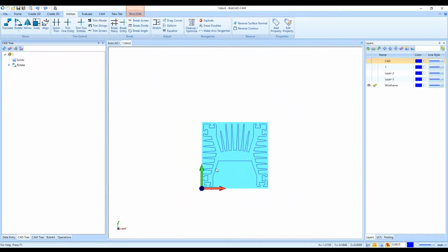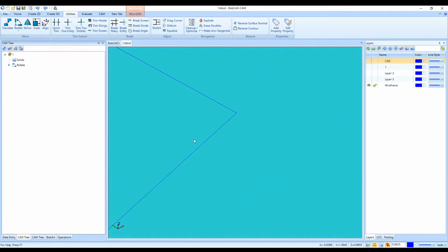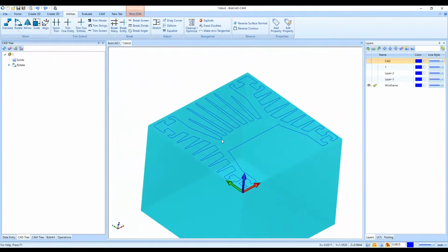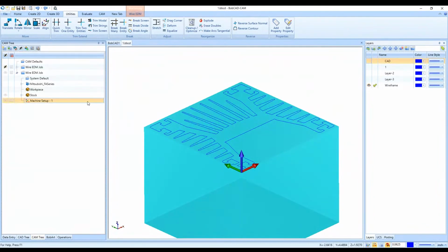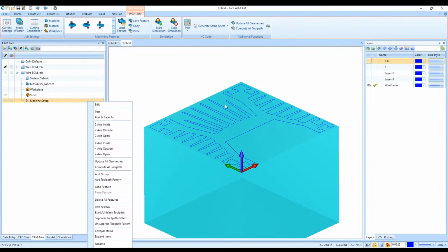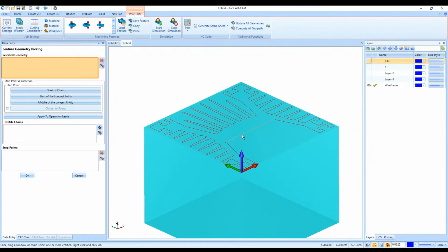So that's why I tend to chain select all of my selections here. I just undid that, so now we have the correct geometry. But that's why I tend to chain select everything. That way, when I'm selecting my geometry, I know that I have a continuous chain and that I'm not going to get any issues with the toolpath, any issues with my G code at the machine. That is going to cut the whole shape there.